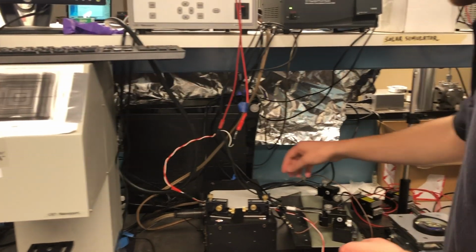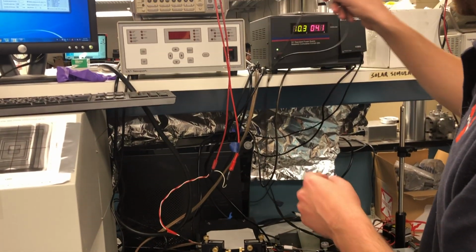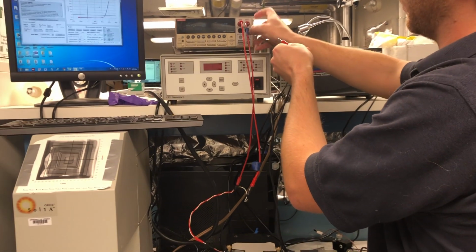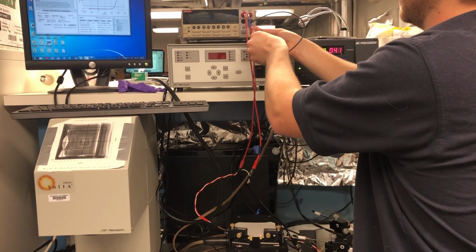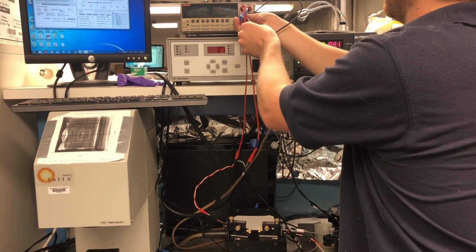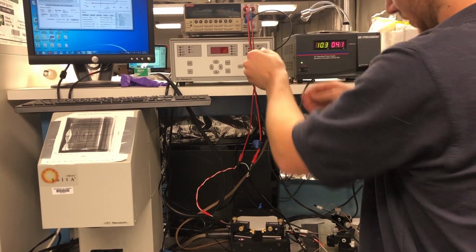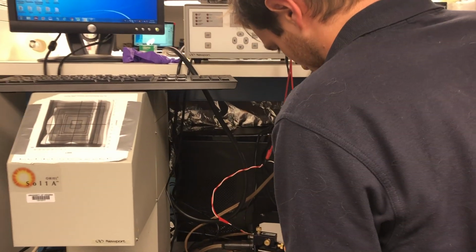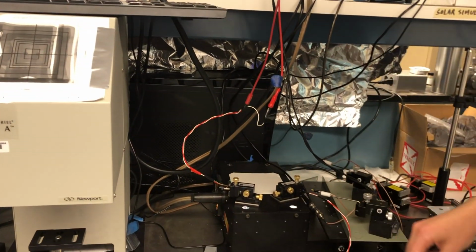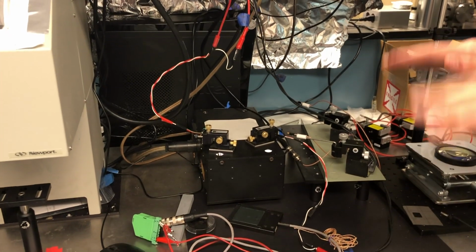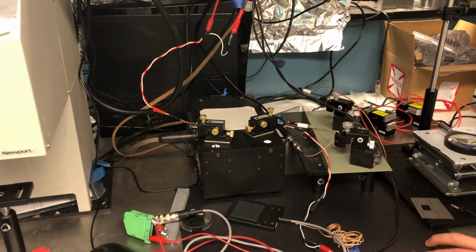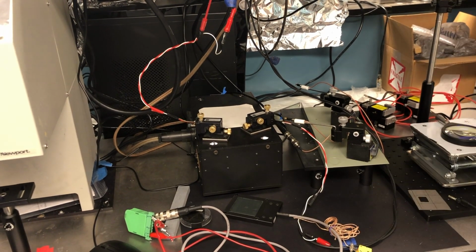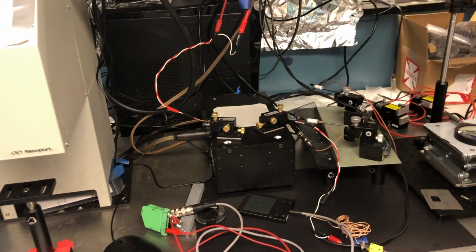And then for our negative probe, which is over here, plug it in first. It doesn't matter which order these go in, because again, they should be the same. But just keep black with the black and the red with the red. And then we'll put that on our cell there. So I've already sort of pre-set the height so that these probes are pushing down and making good contact with the cell. That's important. If you have poor contact, you may not get a diode curve, you might just get noise.